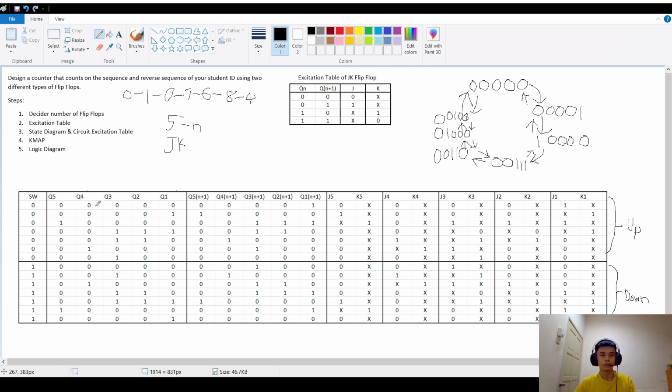We are going to determine which flip-flop is our MSB and which one is our LSB. So you can see here is our MSB, but then we are not using it because here we only need 4 pins. So we only put 4 LEDs in these 4 pins. So here should be our MSB. And Q1 is our LSB.